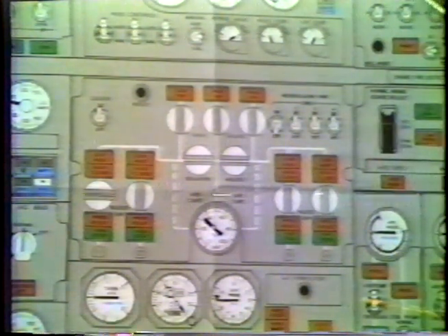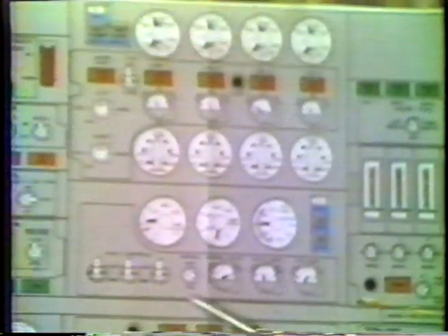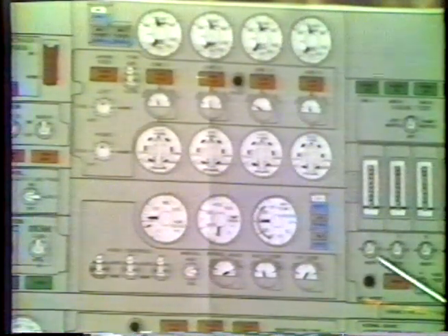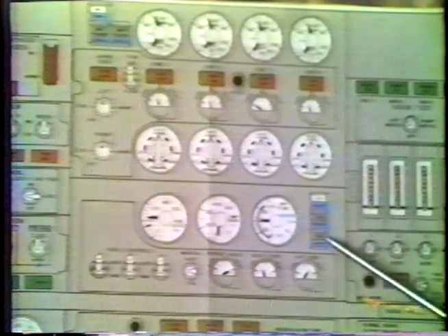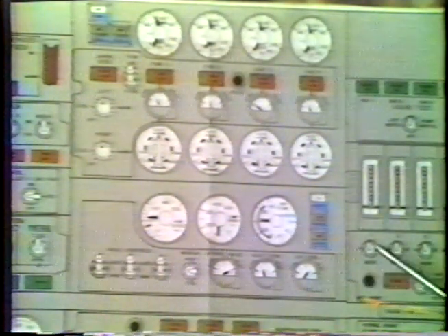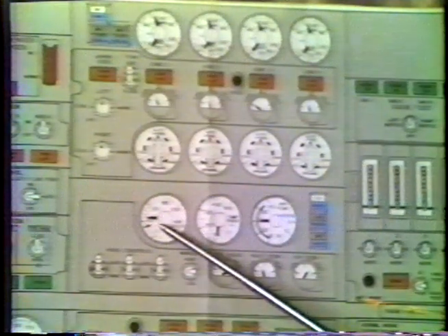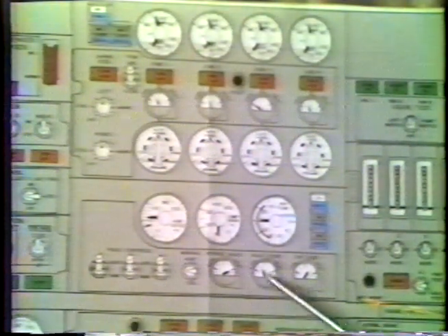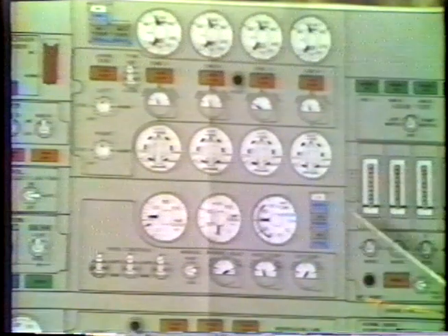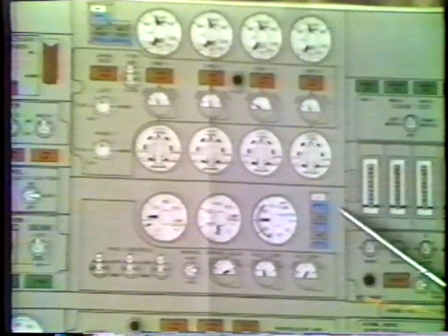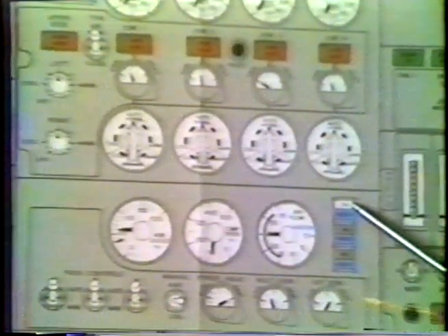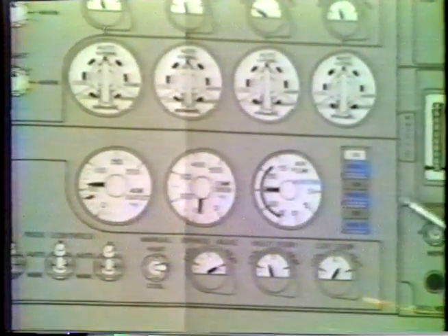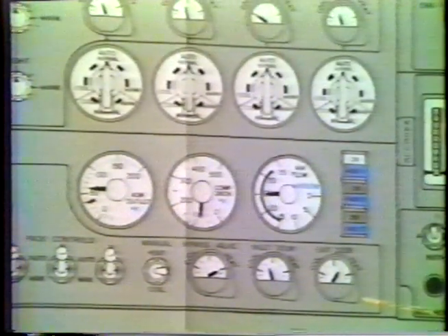Moving up to the PAC control panel right here, we have the controls for the 3 PACs. The 6 indicators, ACM out, compressor discharge, and airflow, bypass valve, inlet door, and exit door, are controlled by the push buttons. When you have PAC number 1 selected, all 6 of these items are looking at PAC number 1. You select number 2, all 6 of them are looking at number 2.